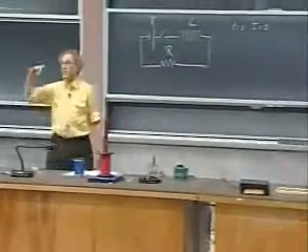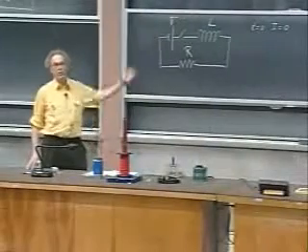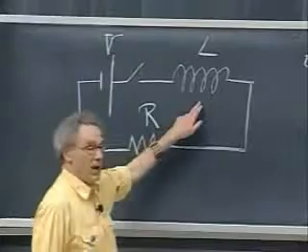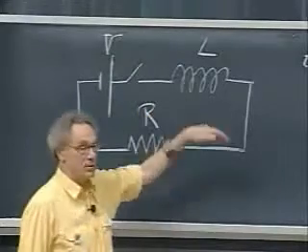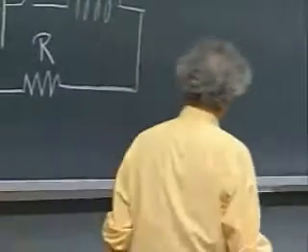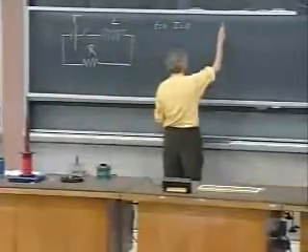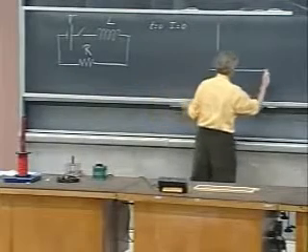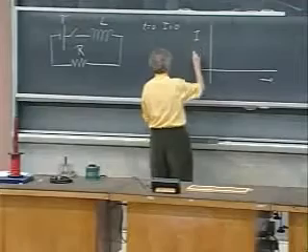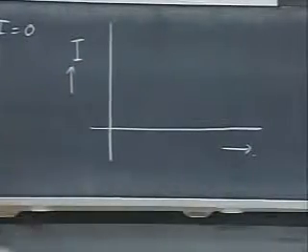the current has reached a maximum value, which you can find with Ohm's law. Because the self-inductance itself has no resistor. Think of the self-inductance as made of superconducting material. There's no resistance. And so without knowing much about physics, you can make a plot about the current that is going to flow as a function of time.